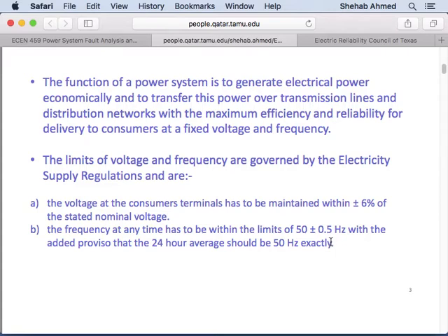That's going to slow it down, right? For you to bring it back to steady state, if you slow it down, that means the frequency is going down, right? The frequency of the generator output is proportional to speed. The back EMF, the voltage E generated by the machine, depends on the frequency of the rotor, right?